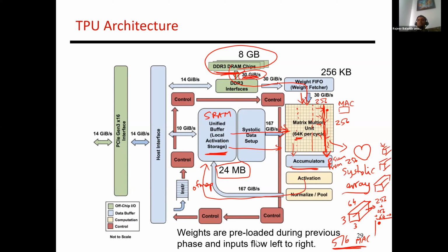And so you have to keep doing that. Okay, then the next question is, what is the precision of the Google TPU? It's coming up shortly on the next slide. Does it accumulate the MAC operations or the multiplication operation? In each one of those cells, you're doing one multiplication, and then you're adding it to whatever came to you from the top. The result of that multiply and add is then sent to the bottom. Okay, so hopefully that answers the question of what exactly is happening with these accumulates. Yeah, and I'll get to the precision shortly.